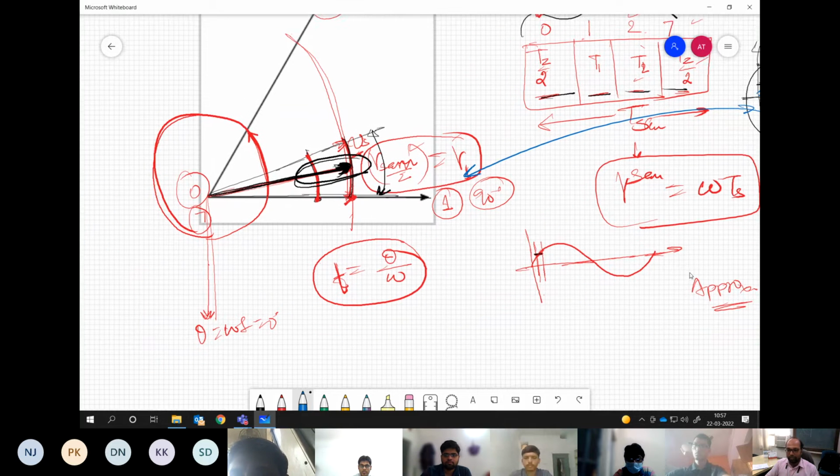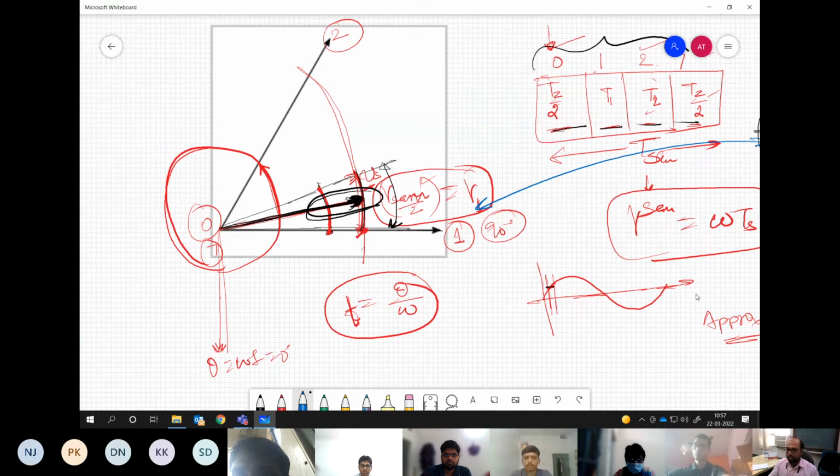Think about it again. I leave this description I have given you over here for you to think on a little bit more, and then you come back tomorrow with your understanding of what you have understood by this point. What I am trying to say is that if you have to realize a voltage vector at this location, gamma sample by 2, or at any location, you need to apply the voltage vector symmetrically around this.